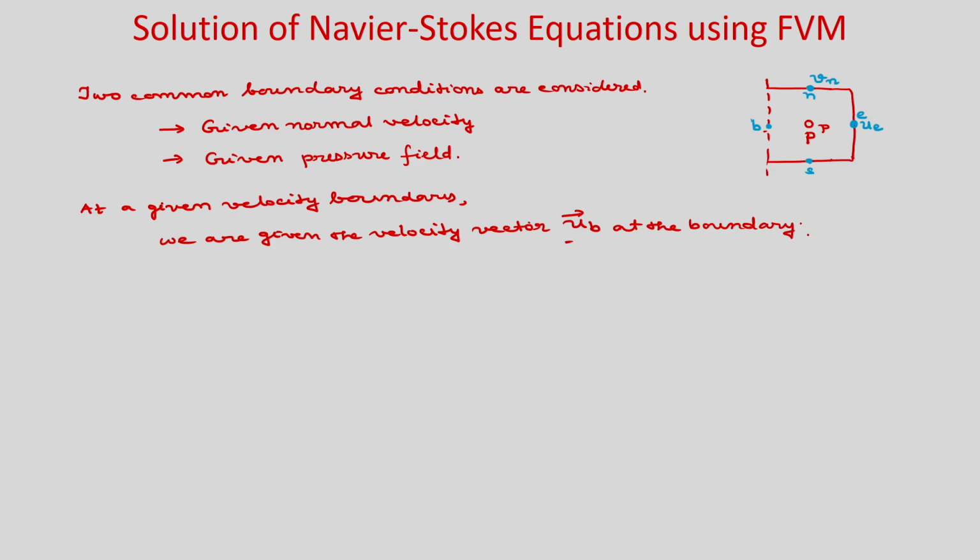Okay. So, now if it is inflow, then velocity will be provided. If it is outflow, if you know the outflow boundary condition, then also you can use the velocity is specified, or we can use some outflow boundary condition, and if it is a wall, then there will be no penetration through the boundary and velocities will be 0.